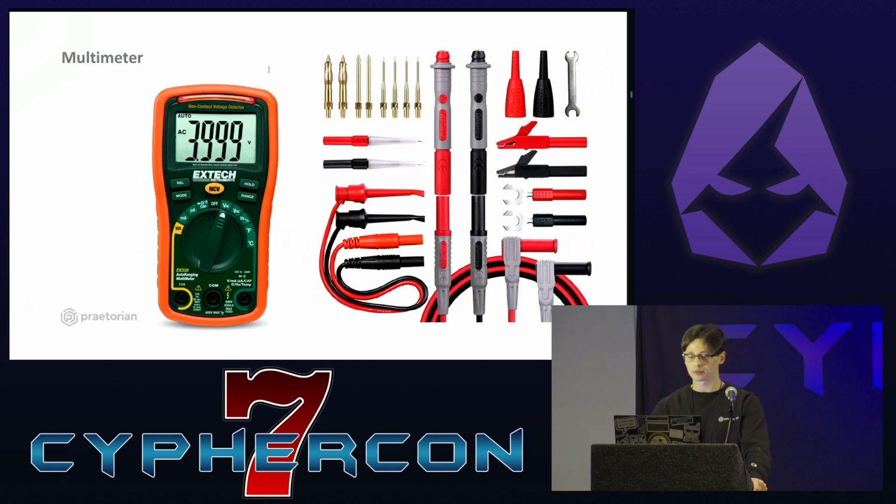A multimeter is going to be one of the most pivotal pieces of equipment in your toolkit. As the multi might suggest, it can do all types of different measurements: voltage, current, resistance. But the things you're going to be using the most are checking the voltages of different signals, different pads, and also doing continuity testing. A lot of these meters will have a mode where if you touch the two leads together, it'll either display something on the screen or make an audible beeping noise.